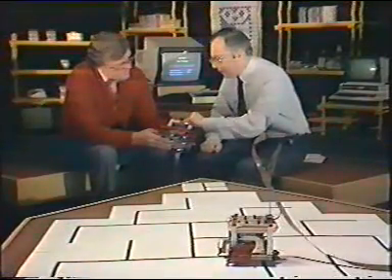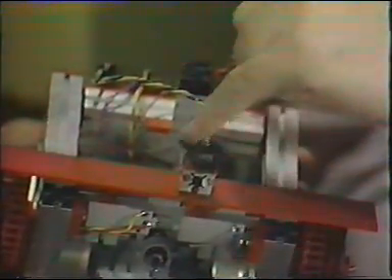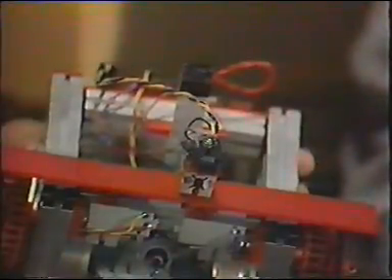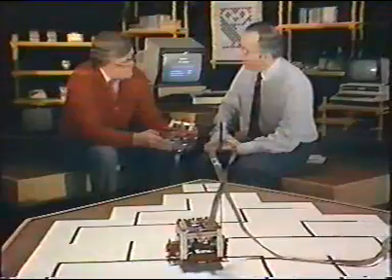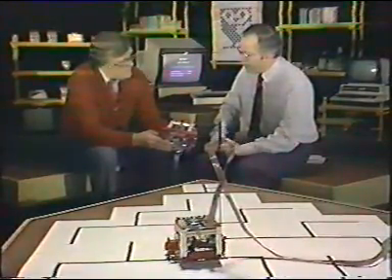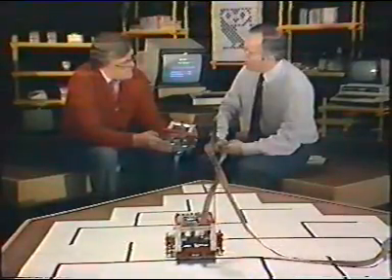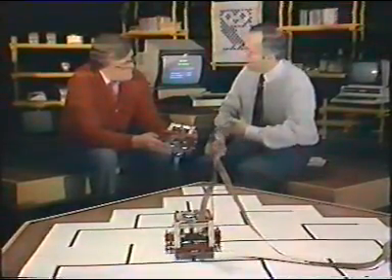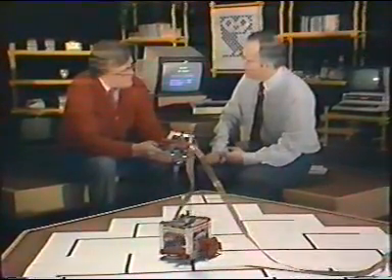This one's really rather different. This sensor emits infrared light on this side, which is reflected off a surface, and then the infrared is picked up here. So it can follow either a white line or a black line and determine which it's on. That's actually an analog device, but the computer senses whether it is above a 50% level, whether it's above grey. If it's brighter than grey, it says that must be white. If it's darker, it must be black.